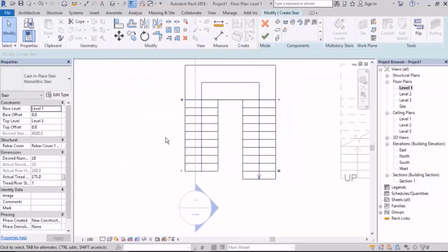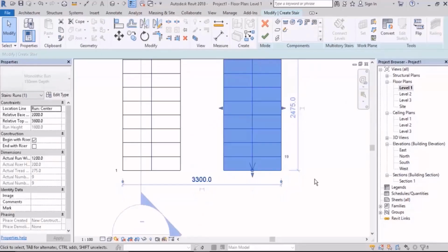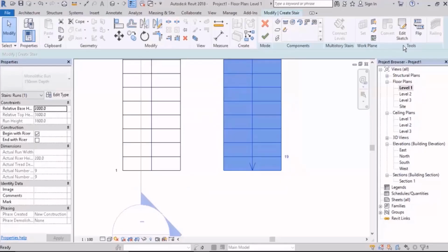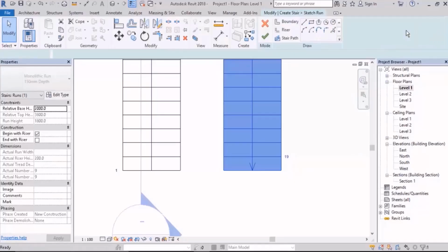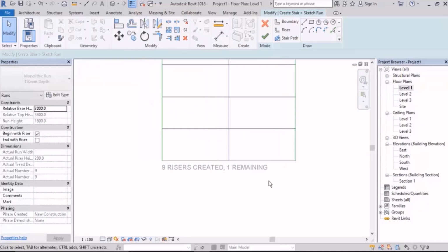This is that. Now we need to go and add one more stair. Please pay attention to this part. We need one stair. You see 20, 19. Now here it has two forms. Either your staircase is sketch or it's automatic. Do you remember from the previous session? If the staircase is automatic, how should we add one more stair? That's right, using the spot, not the arrow.